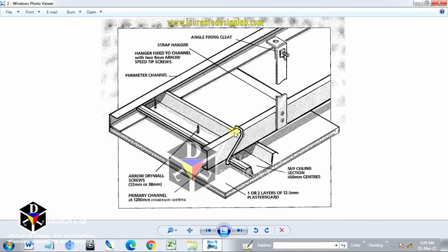So it could be level 3 also, in which the structural system consists of 3 levels. Level 1, the way it is shown here, the furring channel, level 2, C channel, level 3, something else. It depends on the kinds of ceiling or the manufacturer of the ceiling, how they design, how they give the manual to fix it. Now you can relate the design which you are doing in the software with the construction of the ceiling. Knowledge of both the items is required to actualize your design.